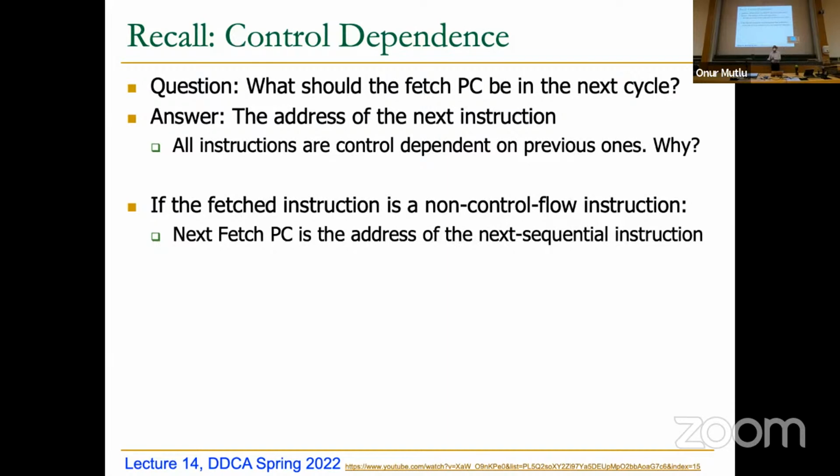So then what do you fetch next? By how much should you increment your PC for the next instruction to fetch in the next cycle? And next cycle is not next cycle if you're superscalar. If you're superscalar, next cycle is this cycle. So superscalar complicates the branch prediction also. You have control dependence even more, right? So existing processors do all of this today, basically. So the complexity, although people have actually put a lot of effort to solve these questions for sure.